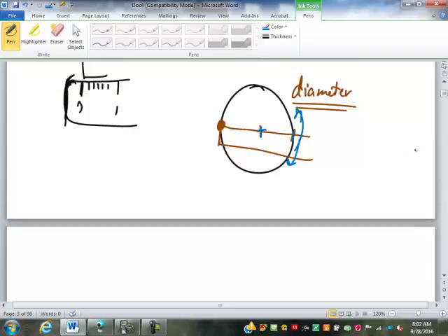And in practice, if you're measuring a circle, generally it's going to be a solid object, not something printed on a piece of paper. So you're just going to take a caliper and clamp the jaws of the caliper around it, so you're definitely getting a diameter then. We're just looking at when we're doing this on paper, how can you make it work?